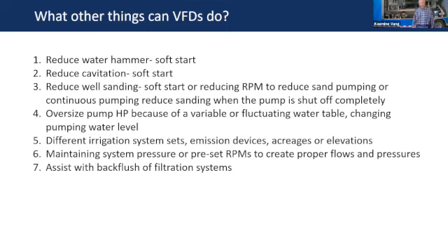You can set it up to wind up in a few seconds or slowly over minutes if you want, with a VFD or with a soft starter, but we're talking about VFDs today. During that time, a lot of times you'll get some cavitation when you do across-the-line starts, especially with booster pumps and things like that. It's good to maybe start it up slowly so you don't get that cavitation and damage your impellers. So soft start can help with that.